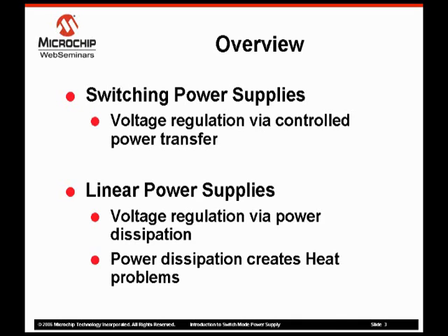The linear regulator works like a variable resistor, dropping the input voltage to the level required by the output. To meet all the conditions of worst case, a linear supply under typical conditions may dissipate as heat an amount of power equal to the power consumed by the load. Under high input voltage conditions, the power lost as heat dissipation may be double that of the load.